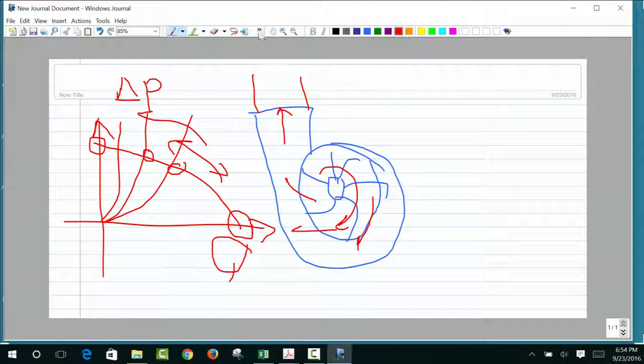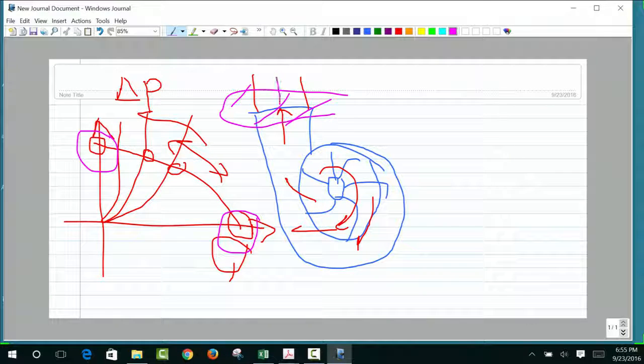So that's what every pump is characterized by: the maximum flow rate it can get if you don't put any pressure on it, and the maximum pressure it can generate, where it's like, I cannot deliver a single molecule for you, it's just too much for me. And it's not just that imaginary situation where I build a wall over here and block it. It's that the pipe is so long, or so high, for example, that the load curve is almost vertical. That's where you approach the point where the pump cannot deliver.